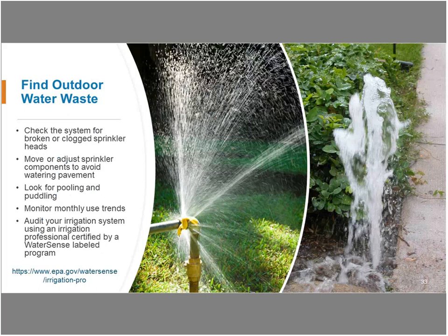And then also, if you have irrigation outside, I encourage everybody to look at the water waste within your irrigation system, because it can be significant. Sometimes it's a huge amount of water. The picture on the right side is what we call a geyser, which is where a broken sprinkler head will just have water shooting out of it, and it can be a lot of water. Other times it's something within a pipe, the joints within a pipe that are leaking. And sometimes it's below ground if you have the pipes underneath.